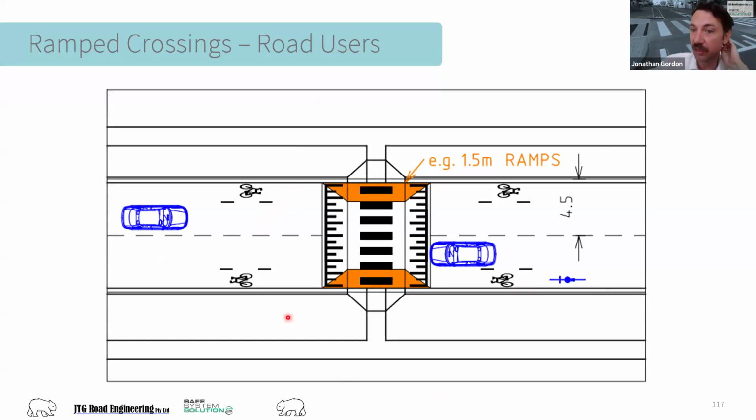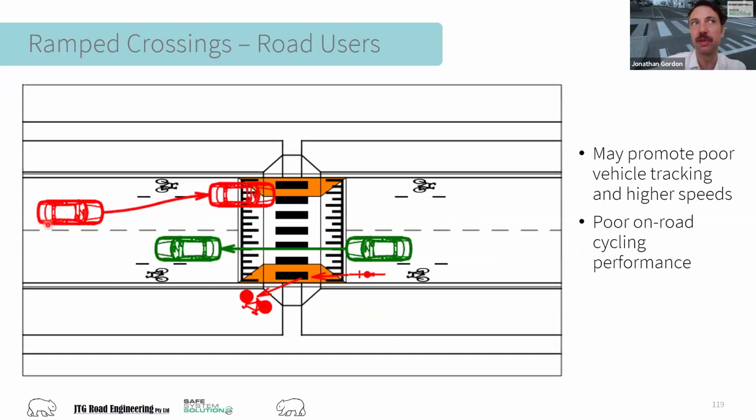There's just a few other concerns I'd like to highlight for us, and that's arrangements such as this. So for this example, I've got 1.5 meter ramps that are conforming and meeting the requirements for whatever we needed to achieve. But we've also got some vehicles and cyclists here, and I'd like to highlight a few concerns. Again, it's similar to me discussing how a vehicle for the cross-sectional example earlier might choose a different path to negotiate these at effectively lower ramp heights. And again, I do not drive like this, but you can see it out there, and I hope you don't drive like this. People may choose to actually go out wide to hit the ramp a little bit faster with the less ramp height for their left wheel in this scenario.